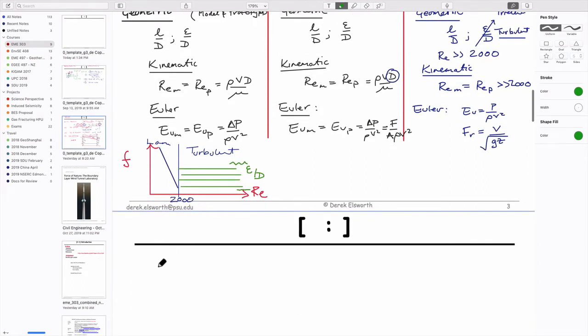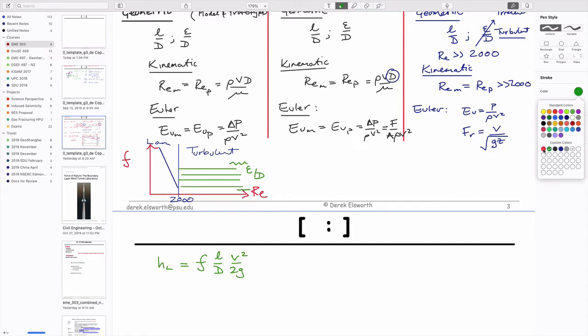And we said last time that this friction factor contributes to the head loss in the system by an expression which scales with some geometry of the pipe and also the inertial part of Bernoulli. And the only reason for maybe doing this now is that in the weeks to come, when we look at external flows, we'll find that the drag that gets applied to an object as air flows or fluid flows around it is defined in terms of a coefficient of drag.